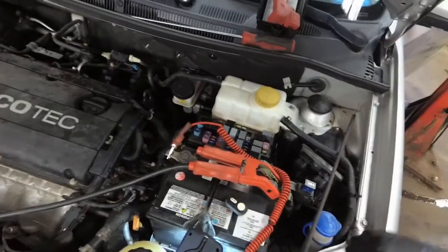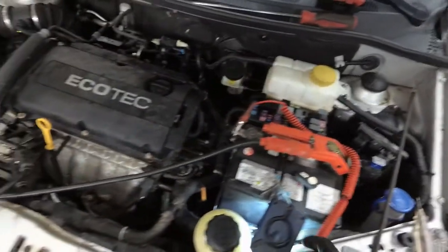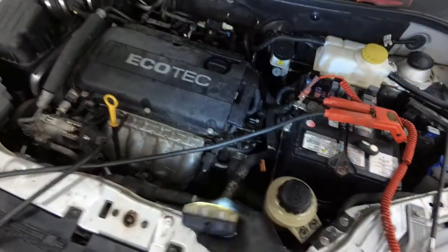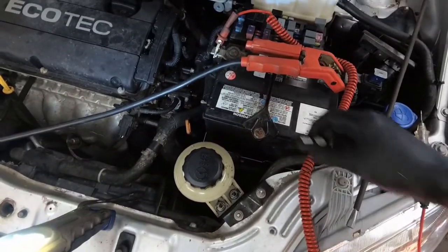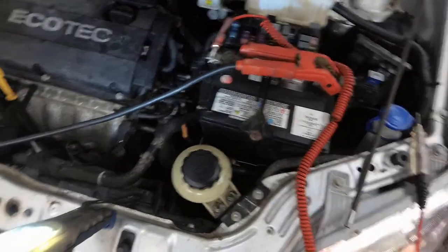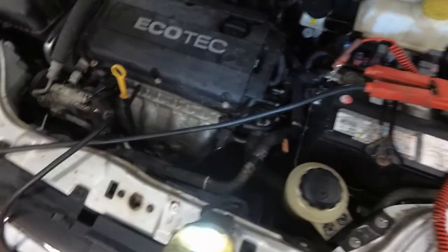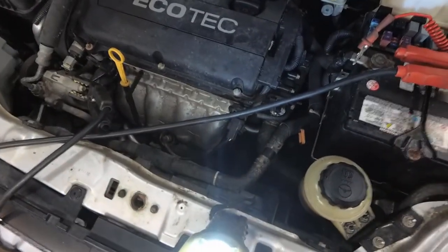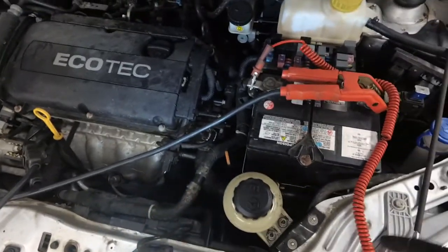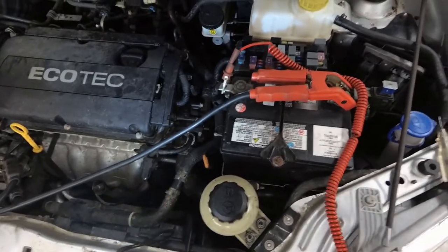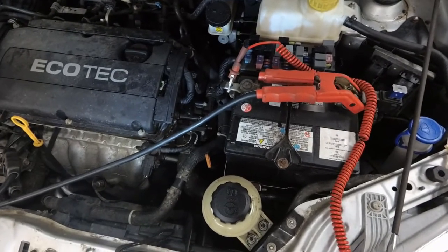It's funny they didn't work in the 70s. Why would they expect them to work again in the 2000s? So I'll see about that dropping resistor. I'm sure that that's the reason why the fan doesn't run on low, although it should run on high and prevent it from overheating. But we have a coolant leak, failed thermostat, failed dropping resistor, and the power steering rack that needs to be replaced.